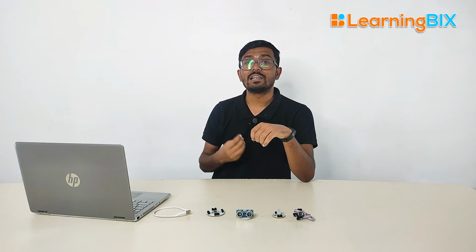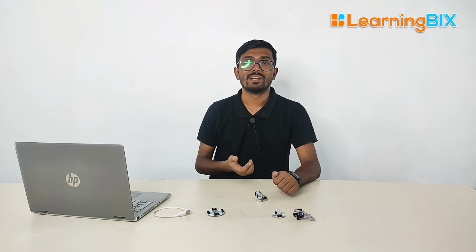So right now I will initialize two things. That is the sonar sensor as well as your serial monitor, so that I can see the output of it. As I told you, it will measure the distance. Whatever value of the distance it gives me, that is the response or the feedback, I want to see it, whether it is 1 centimeter, 1 meter, 100 centimeters, or whatever the value is, so that I can use those values in my project. For that I need a separate window, that is your serial monitor, and in that we are going to view it. So let's write the code for opening it.